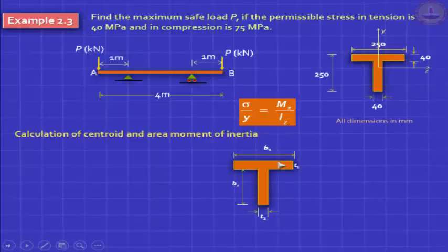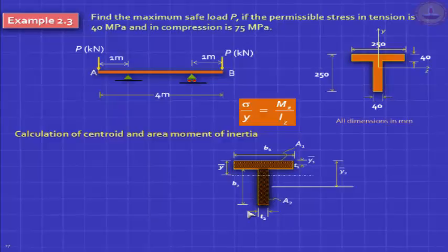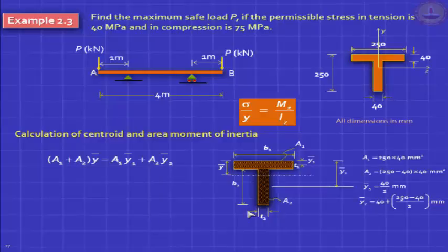And so you need the property I here. For an I section with these dimensions, you know how to calculate it. I'm not going to spend time on this. Please do it. Find out the centroidal axis by maybe starting with the top fiber, and you can have two areas, A1 with centroid at Y bar 1 and A2 with its centroid Y bar 2, and find out the total area, do all these calculations.